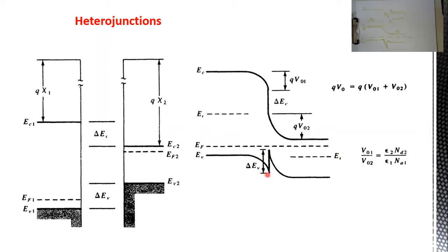And this is one of the phenomena associated with the heterojunction. Of course, this is only one example of a heterojunction. You can have different examples. Simply, you can turn the game to have the N side with a higher band gap and the P side with a lower band gap. So you will find that the spike will be turned into the conduction band, and you can make different shuffling for the inputs and get different energy band gaps.